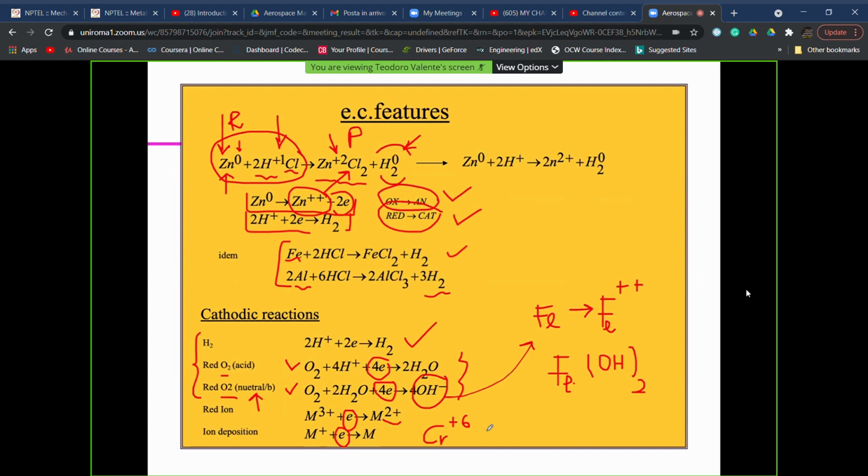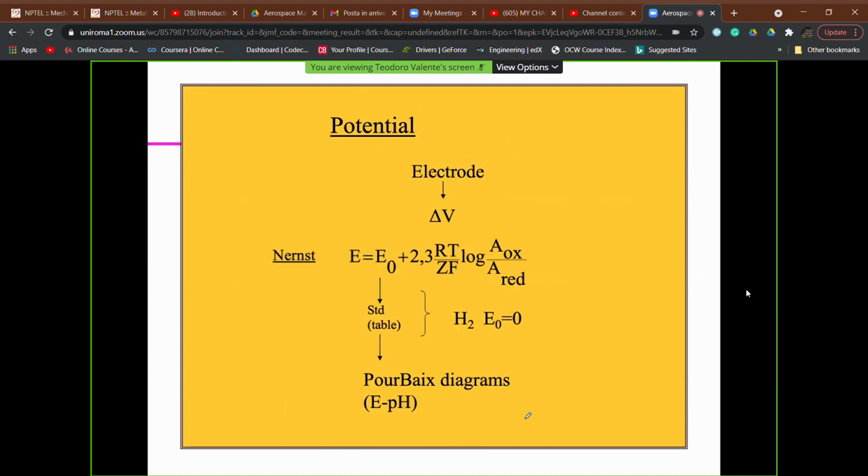They are able to give the formation of hard chromium coatings, because these hexavalent chromium ions can capture 6 electrons, so chromium can reduce to the 0 oxidation number, to the metallic form, and if this happens on the surface of a general component, we could have coatings based on metallic chromium, that is the case of hard chromium plating.